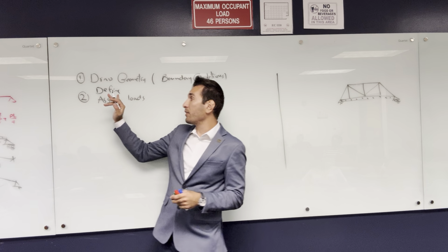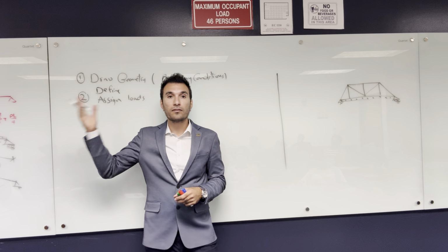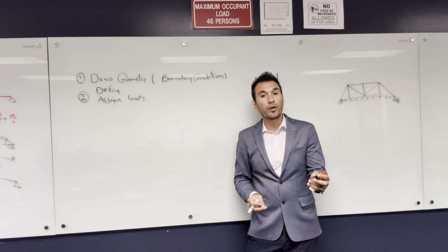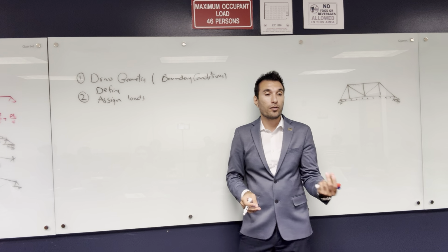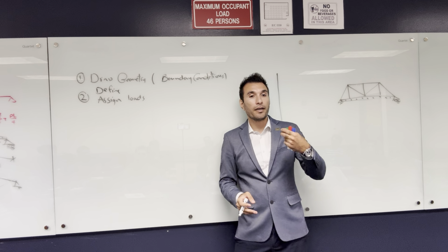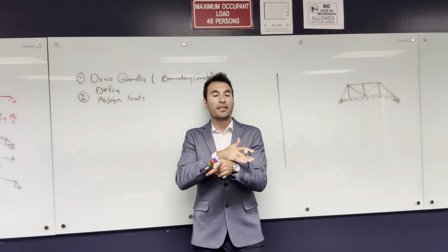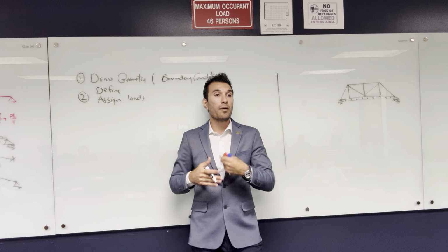So we do something called definition. We define the load. And we tell the software, does this load include own weight or not? Like, I'm going to assign this dead load, and please exclude the own weight from the dead load because I'm going to put it in myself.